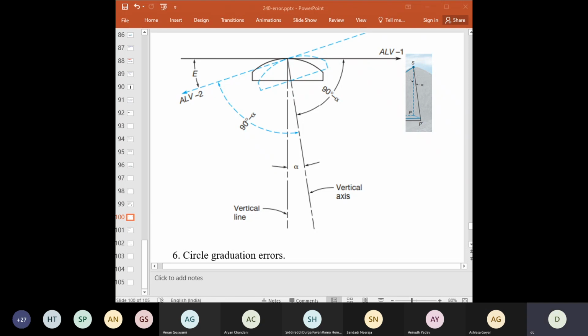So instruments which are equipped with a single axis compensator can only correct the vertical axis, but those having a dual axis compensator can do both. And the automatic compensation is a very delicate part of recent instruments.